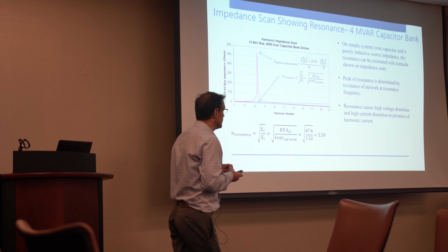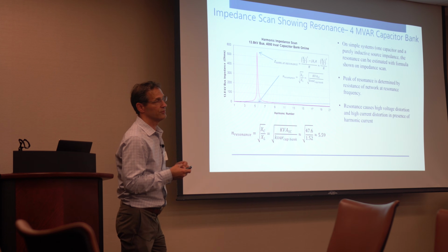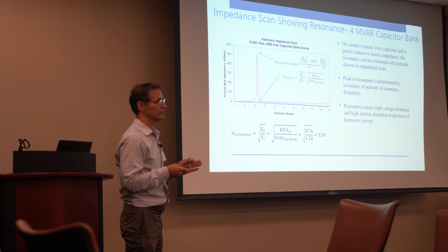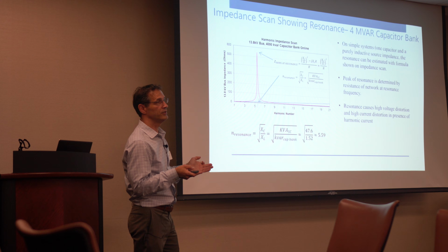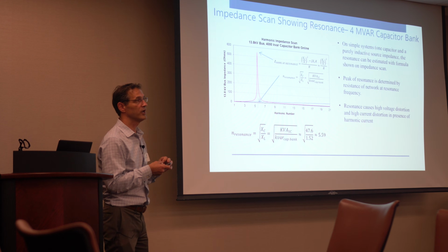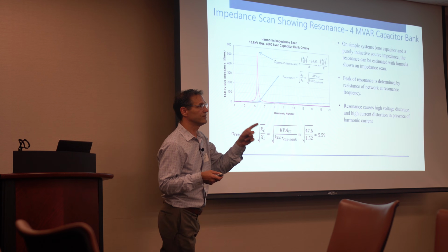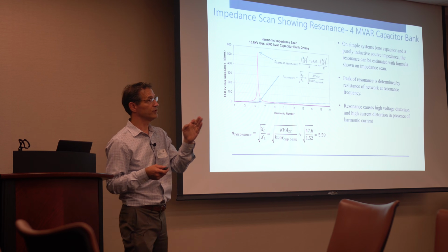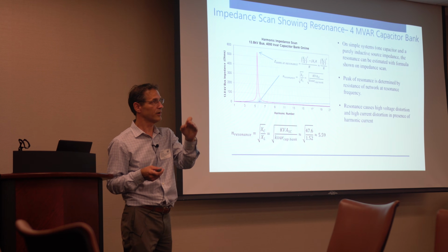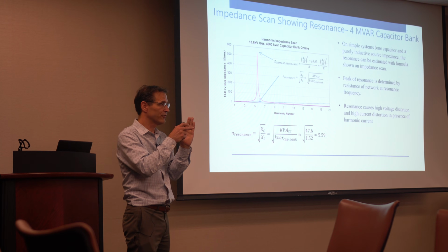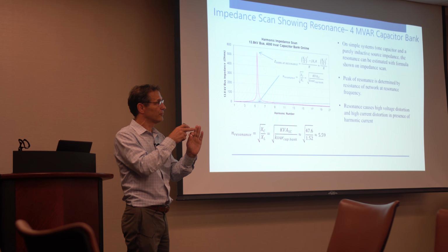In this regard, when you purchase a high-pulse drive, the premise behind buying that high-pulse drive is that you don't want 5th and 7th harmonic current. You might not want 11th and 13th. Maybe you bought a 24-pulse drive, and theoretically speaking, you wouldn't have 5th, 7th, 11th, 13th harmonics. Your first harmonic would be 23rd, right? Plus minus 1 is the formula for figuring out that harmonic. So 24n plus minus 1, so you'd have 23rd and 25th.